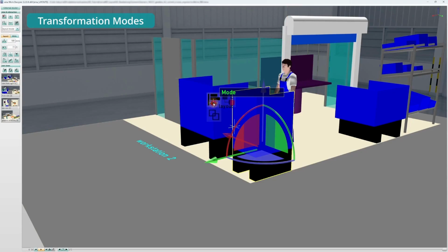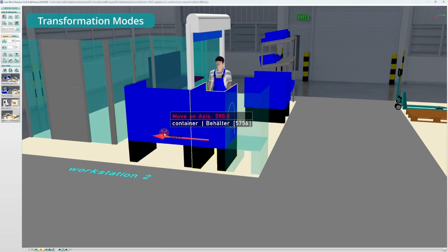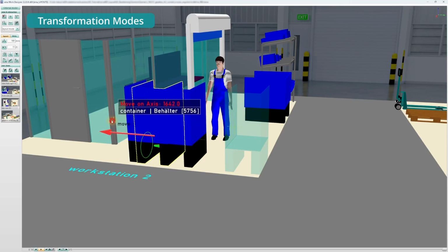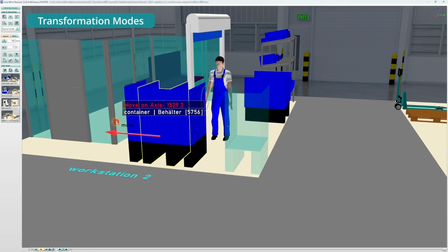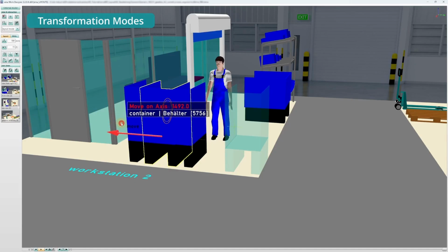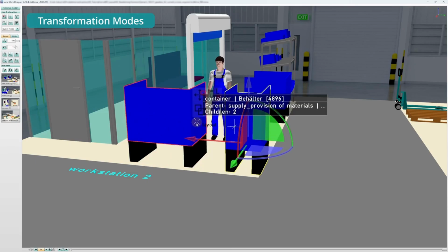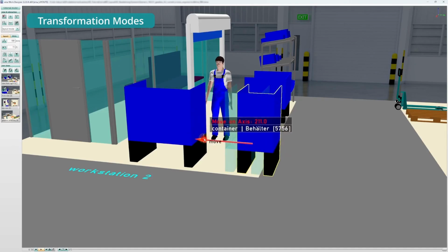When an object is manipulated using the snapping mode, objects are automatically oriented to nearby objects. Therefore, the green helper planes and arrows highlight to which face of the current reference object the manipulated object could be arranged. You can place objects in the middle of other objects using the orange helper markers. With the free manipulation, the object can be moved freely and the limits set in the layout settings are ignored.